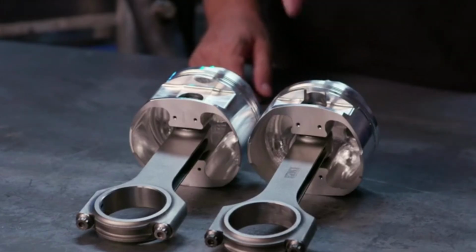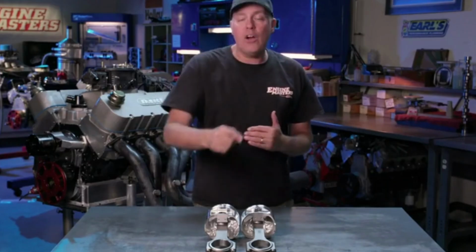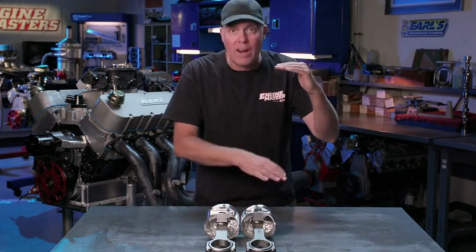The short rod is faster in mid-cylinder on its way up, and it is faster across top dead center. It spends less time with the piston dwelling at top dead center than the long rod. The long rod tends to slow down the piston speed at mid-cylinder stroke, and it also makes the piston dwell longer at top dead center. Inversely, the long rod makes it dwell more at top dead center, but less at bottom dead center. And the opposite is true with the short rod.